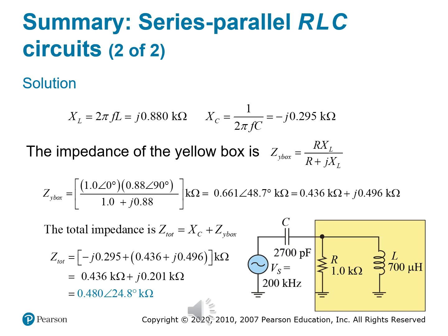Notice how the capacitor's negative imaginary reactance pulls the phase down, but the parallel inductor resistor pair lifts it back. So the result is this modest positive phase angle, just shy of about 25 degrees. And there's a real world insight. This kind of analysis is what lets you design filters, again, lets you design tuning circuits, and a whole lot more. And it all comes from combining the fundamentals.